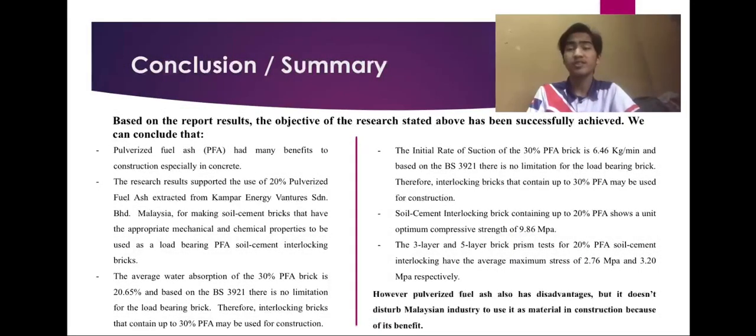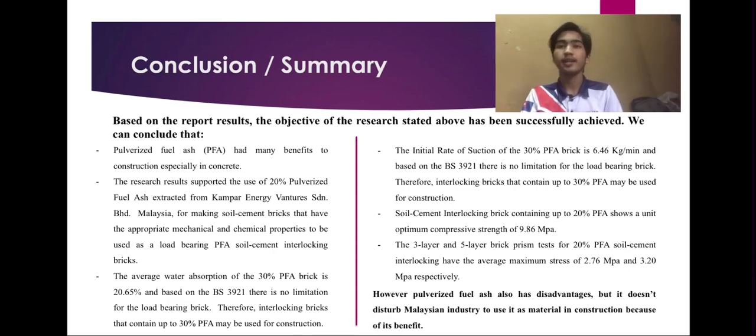Based on the report results, the objective of the research stated above has been successfully achieved. We can conclude that pulverized fuel ash (PFA) has many benefits to construction, especially in concrete. The research results supported the use of 20% pulverized fuel ash extracted from Kapar Energy Ventures Sdn Bhd, Malaysia, for making soil cement bricks that have the appropriate mechanical and chemical properties to be used as load-bearing PFA soil cement interlocking bricks.